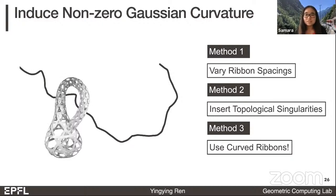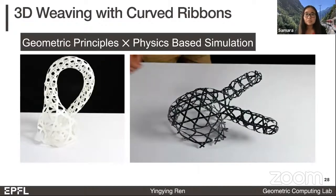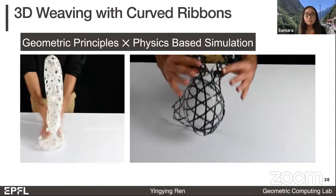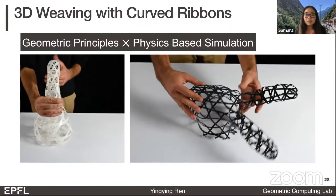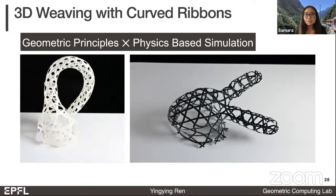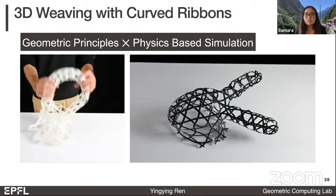An important element that's missing from the existing work on designing woven structures is to incorporate physics-based simulation in the design process. An assembly of ribbons is able to form interesting shapes without any external support because of the complex interplay between the elastic behaviors of the ribbons and the contact forces between them. We accurately track the equilibrium states of the ribbon assembly so that our optimized structure will settle reliably back into the predicted shape, even after extreme deformations, as shown in the videos here.